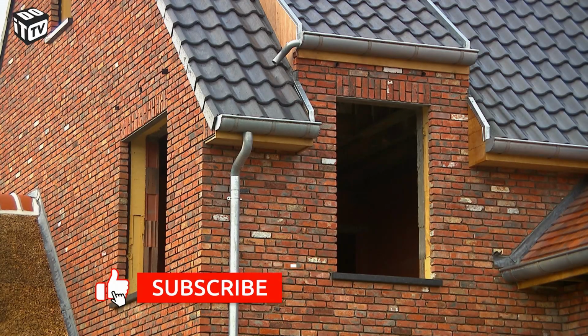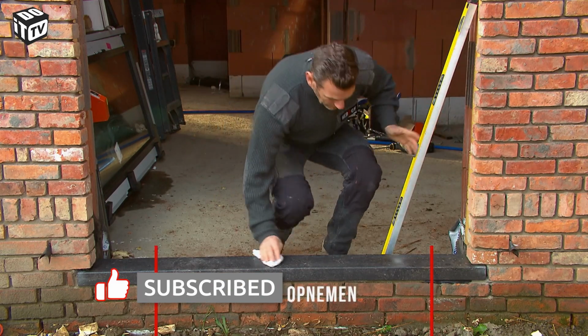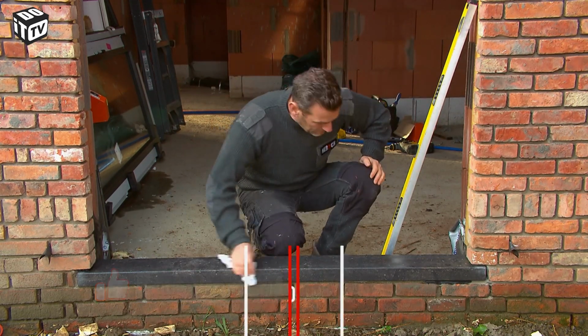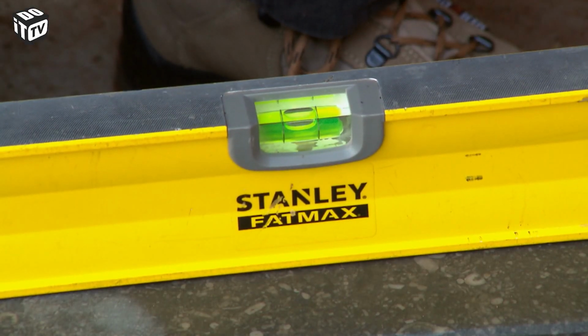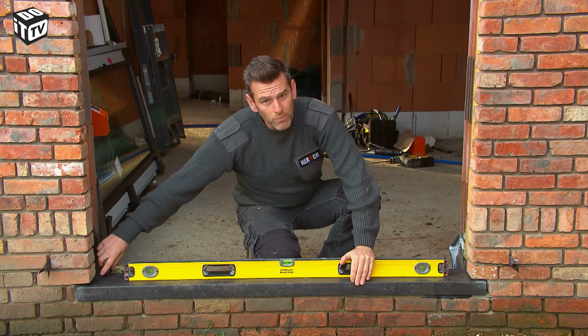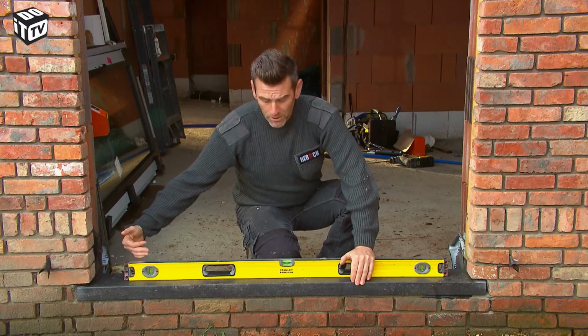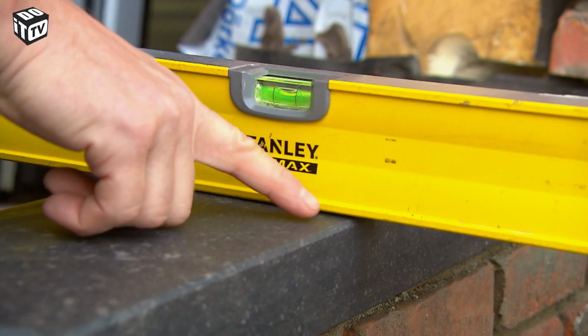To be able to deliver the right type, everything must first be measured accurately. Before Roger takes the measure, he first wants to do a check. The threshold must be installed correctly. The first step is ensuring the threshold is properly placed, meaning we have a 5 cm setback to set up the window, that it's level and makes a 5-degree slope outward.